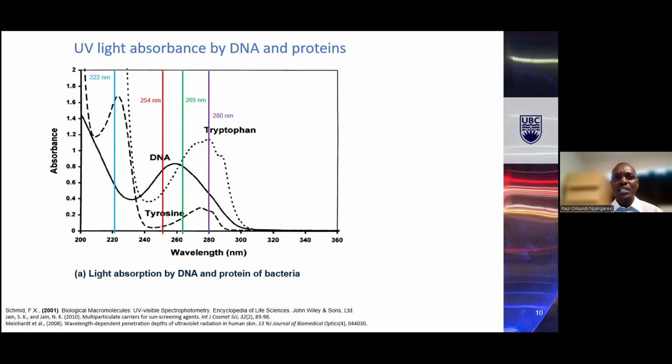And also, how do we really know this UV system has killed most of the microorganisms? If you have done some research, you'll find what we call MS2 bacteriophage. This is a standard microorganism. It's a bacteriophage, a virus which eats bacteria. This is the standard used to check how well this UV system can kill other microorganisms.